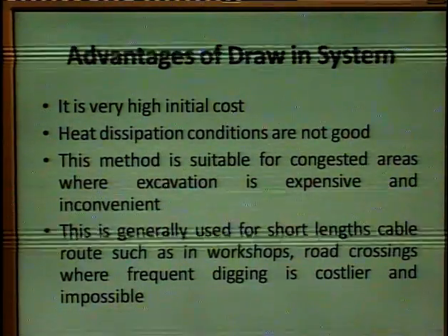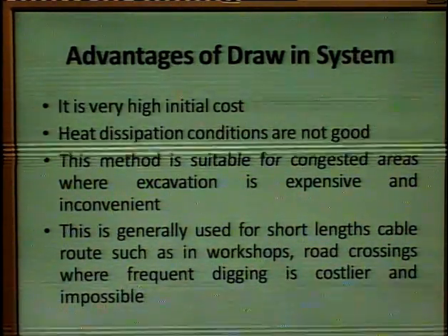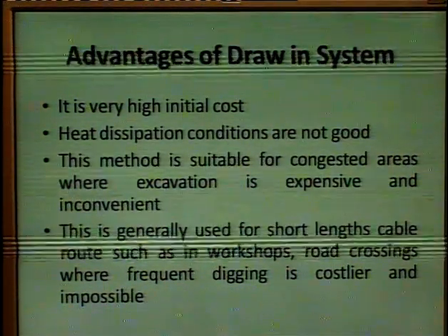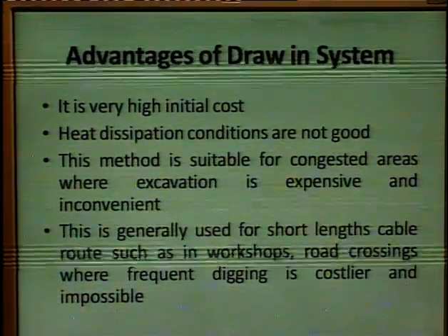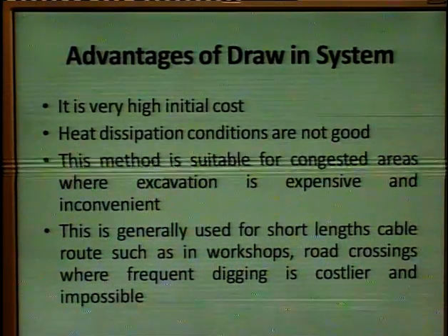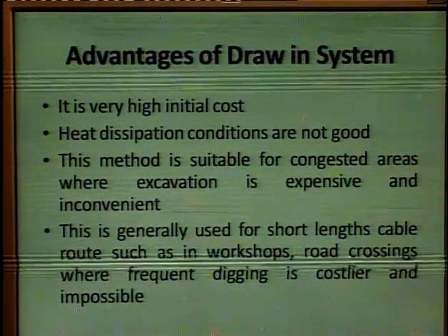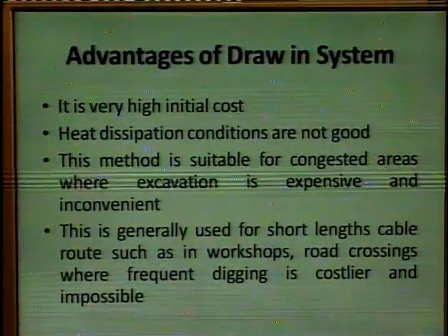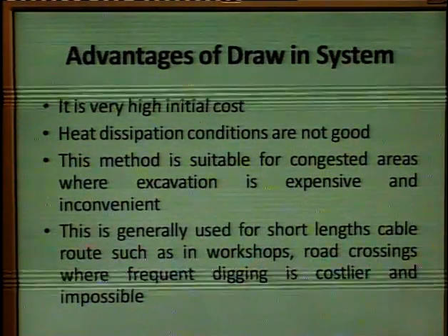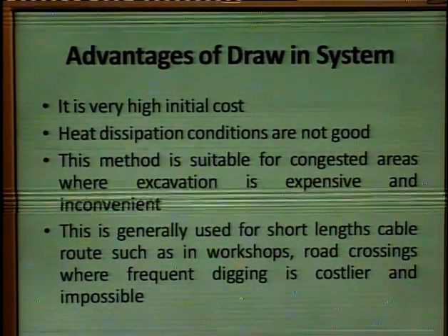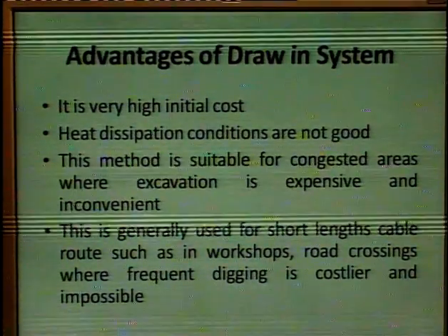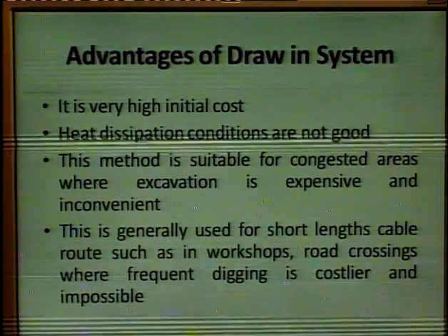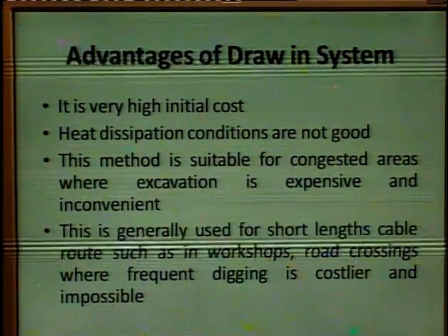So the initial cost of this type of laying is very high, and the heat dissipation conditions are not as good as in direct laying, because the concrete has its own heat transferability properties which are not as good as the soil's.